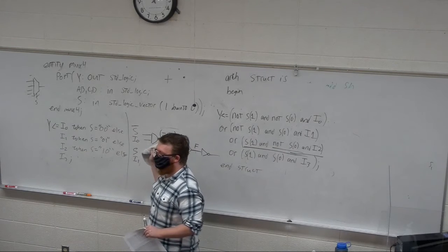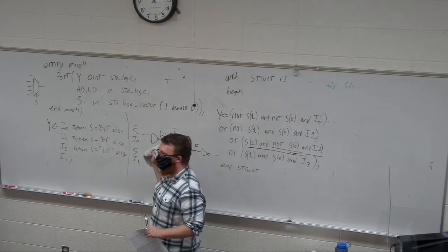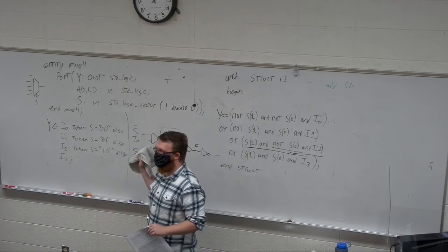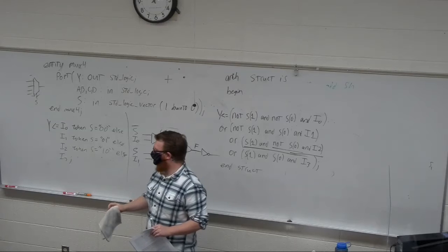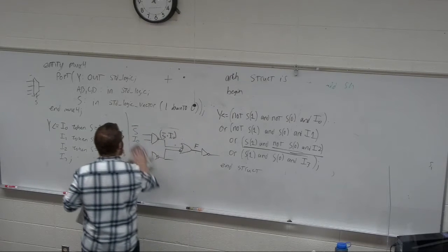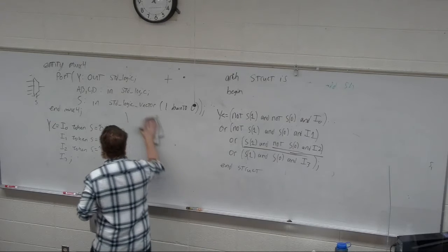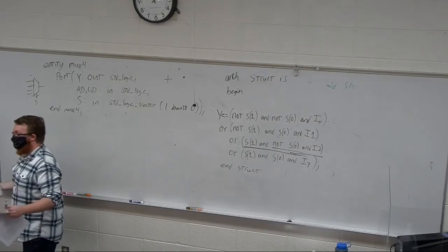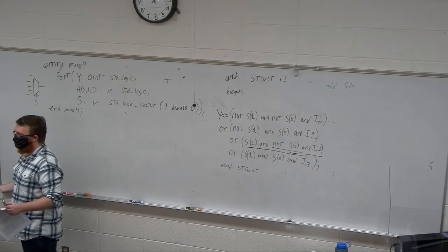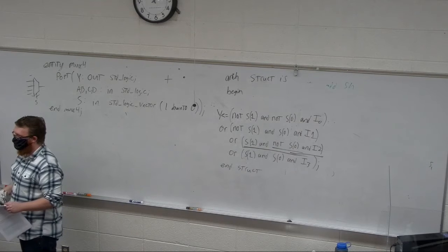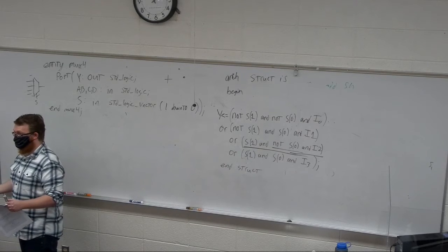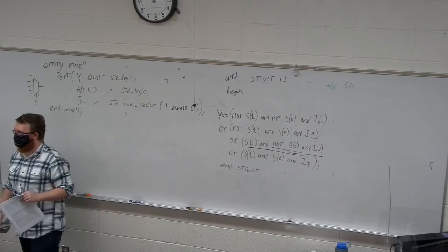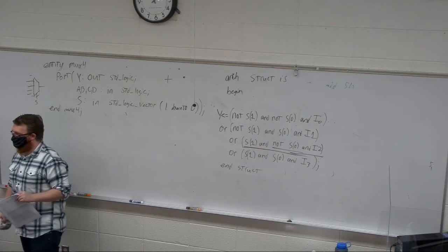There's a question on the homework about how to do an adder. Could you do just the first little bit of it? I can certainly point you in the right direction. When I want to design a circuit, what is the first thing that I would do? Make a truth table, and then I can simply turn that truth table into a circuit and turn that circuit into VHDL. That is a direct method of doing it.